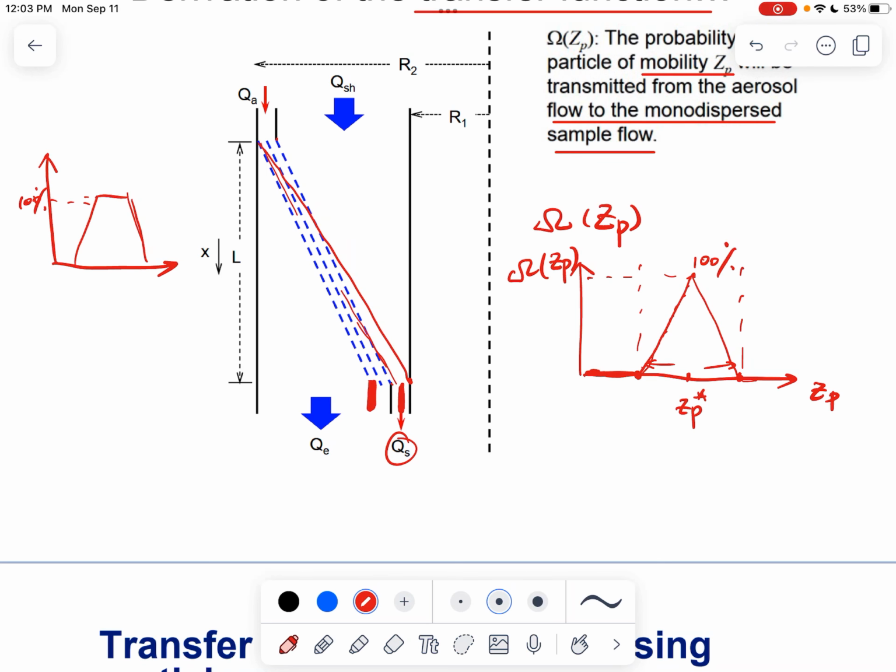So you have the extreme that the particles of the smallest size can get collected here. And even for the particles of the perfect size, only a fraction of them can get collected, because not all of them can enter from this tiny slit here.